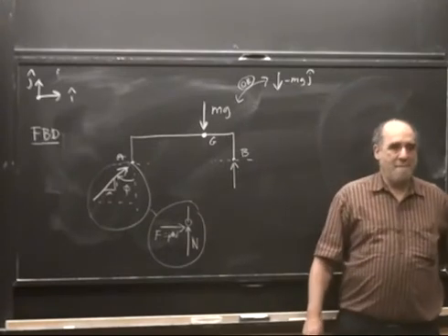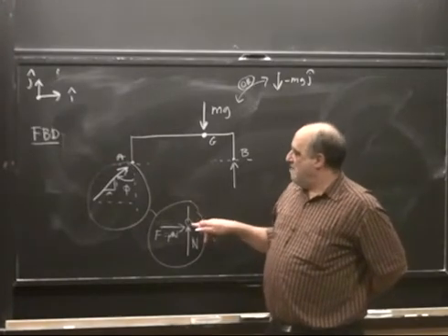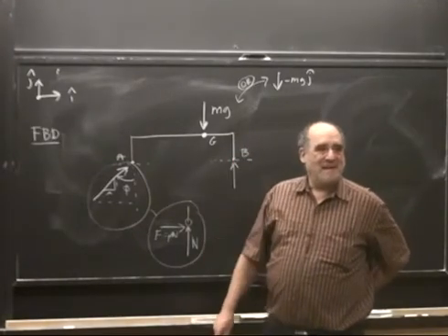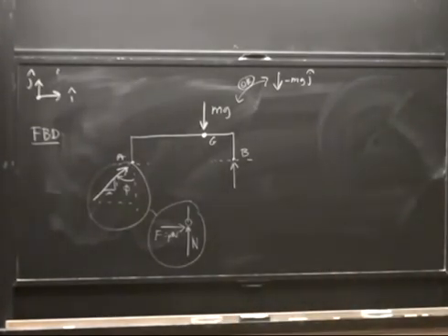How do you know that the sum of those two forces acts at the friction angle? Because the rear wheel is sliding. And when things slide, you have the equation F equals mu N. Remember that screeching sound this car is making? That screeching is coming from sliding. It's actually coming from a friction instability because our assumption that the friction force is constant is wrong. There are fluctuations of friction force, which gives a vibration. But we're never finding that. We say squealing is sliding. We make the approximation that during sliding, F equals mu N. Does that address your question?